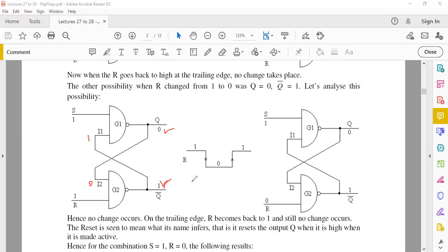So in this state now, if we made our R become low, what happens? Okay, so this is what we see here. Your R was 1, now we are making it become low. We are maintaining our S high. We just change one of the inputs at a time. So if one of the inputs to a NAND gate becomes 0, the output has to be 1. So this is a 1 here, and then your feedback is 1. So 1 times 1, you get 0. So this is a stable state. You feed back the 0 here, so again, 0 times 0, you keep getting 1.